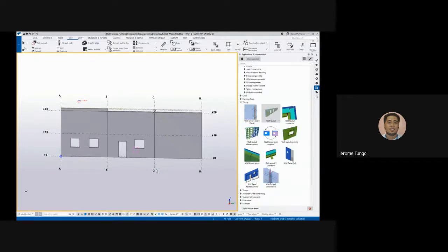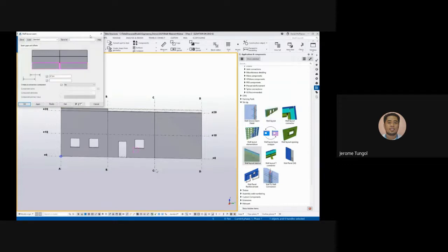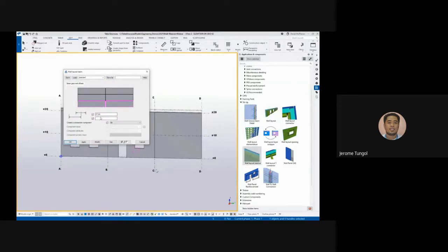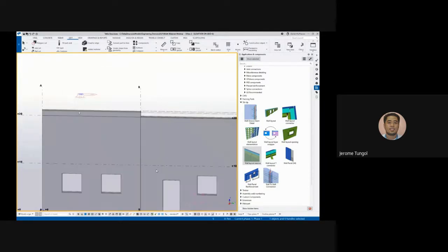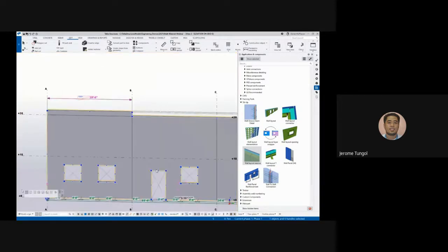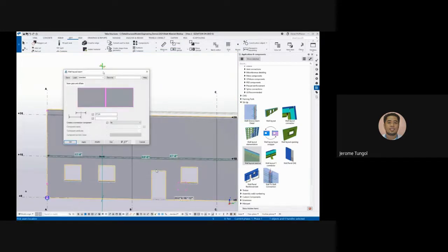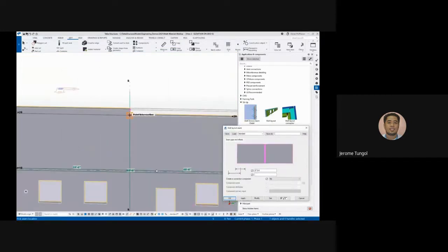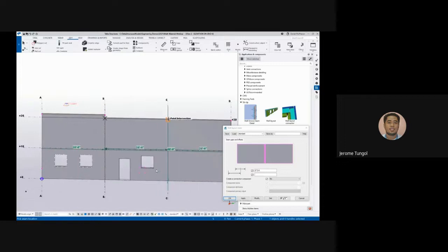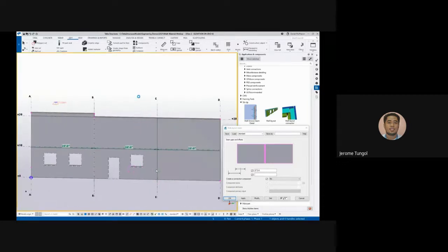And then as you can see, the reference is three wall parts. I have here a wall layout seams wherein you can input the right spaces between the walls. Just simply input the right gap and then, again in the mini toolbar, apply the seams. So it will automatically cut the walls into three parts, also applying the gap you have inputted in the wall layout seams.